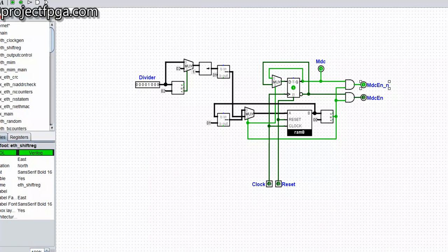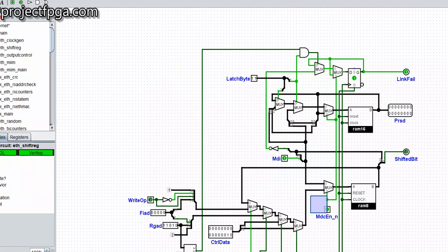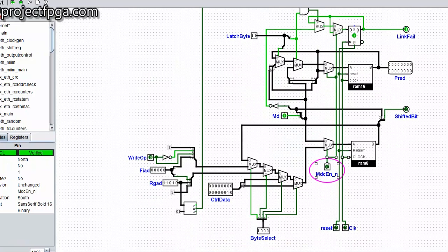So at this shift reg, we are using it again. This MDCEN, whenever it's high, is taking this data here, which is this lower part, and everything here makes up the MDO. When it's 0, it takes this upper one. This upper one is the MDI.